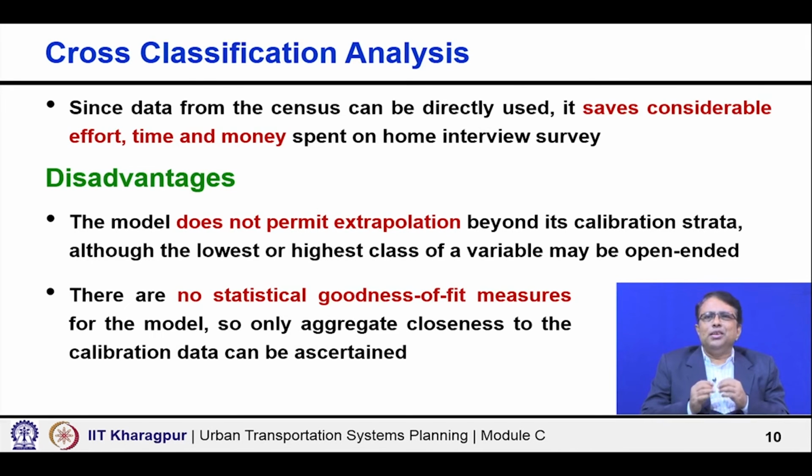For every method there are advantages and disadvantages, and that is why an understanding helps us to decide, given a context. You are doing a work, so look at what is really the intention or the main objective of the work, how much fund is allocated, how much time is given, and then decide which is the most appropriate method. Maybe in one project you will use a regression based model, in another project you may decide that you want to use cross classification or category analysis.